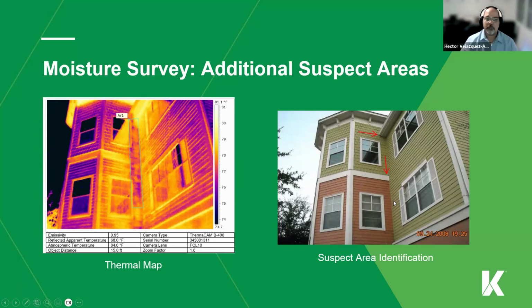When you do an evaluation like this, especially on our end, we go in and take a picture. We can see what appears to be different temperatures on the wall. But why would that occur in that particular area when everything around it is very, very yellow? So we look at the thermal, we see the damage or the possible damage, and we start analyzing the why. Well, you got a gutter system here. Is that gutter system leaking? Probably it is. Is it attached to the building on that corner?